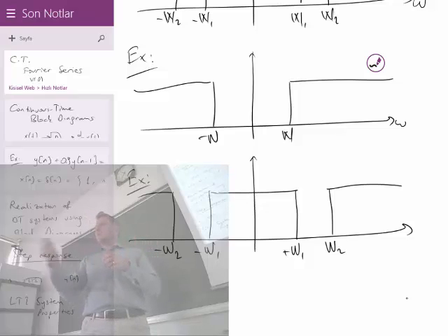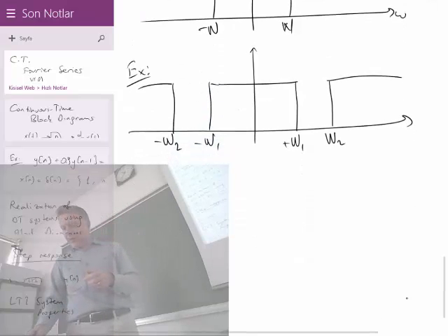It may be a good idea, before trying to record anything, to first suppress that 50 Hertz and not pass it. But it must be a very narrow band stop filter. The design of such filters is a circuits and electronics issue. So you very narrowly suppress 50 Hertz, then you will not notice that 50 Hertz electricity noise, for example.